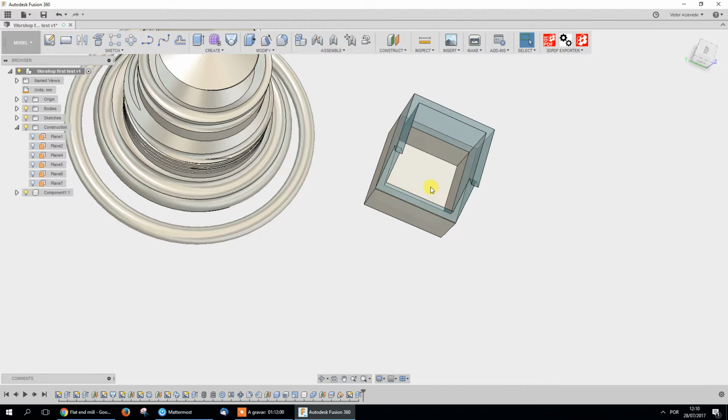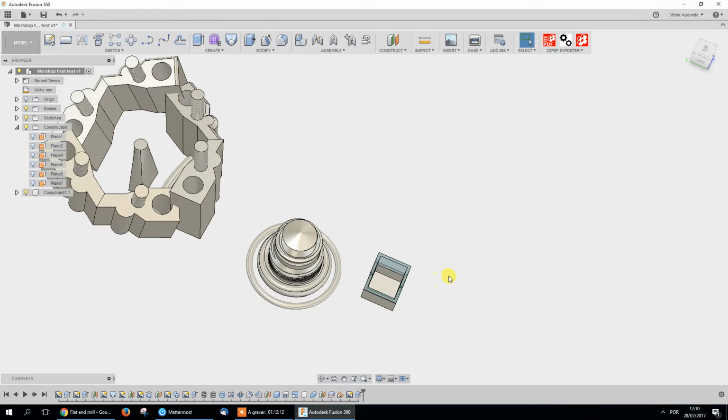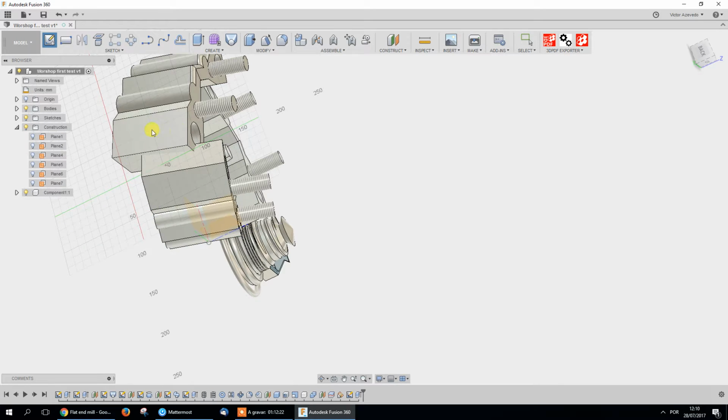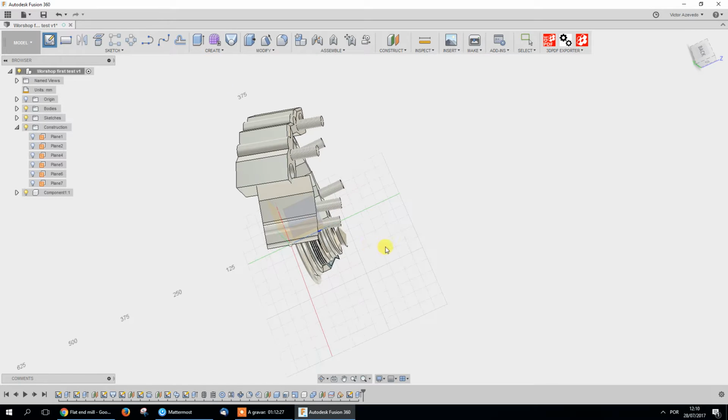I think now that you created several planes, it's a little bit easier to understand. Joanna, it's easy to understand the planes now. Just to remind again, you don't need to create planes every time you want to sketch. You can use the profiles of your part to create more profiles. It creates sketches every time you click on a surface.